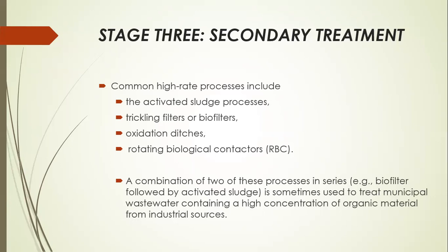As we indicated earlier also, the main treatment options we use in secondary treatment can be categorized as what you have seen here. We can use suspended growth processes, such as the activated sludge process for removal of BOD.